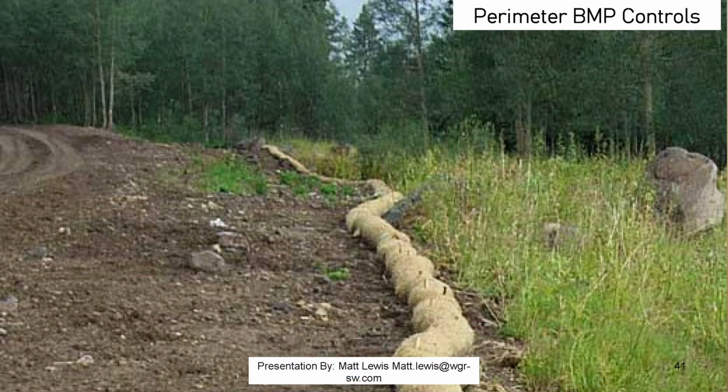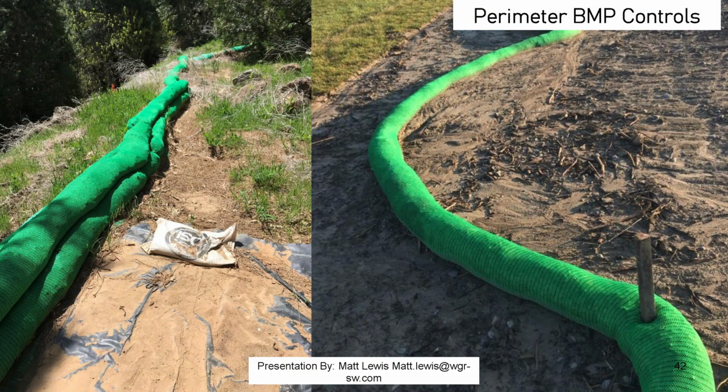And then we just have some BMP perimeter controls, which, as they say, guard the perimeter. We have this standard here on the left, which is staked in more or less every 4 to 6 feet. This is something that an engineer or director will call out. And then up at the top, the next slide, we have compost socks as an alternative, which are nice because they're self-weighting.